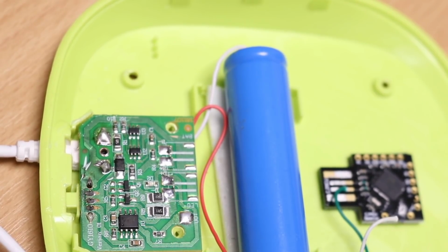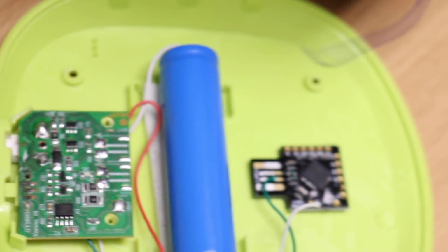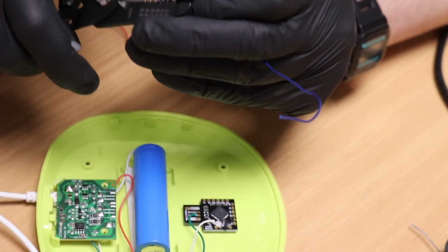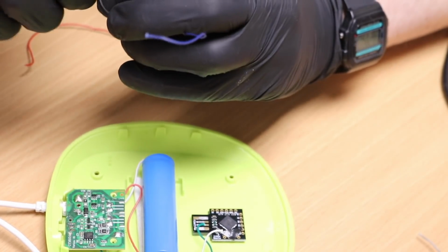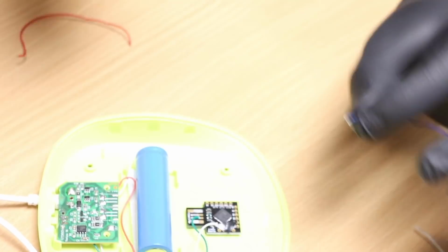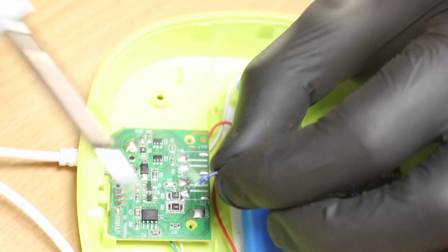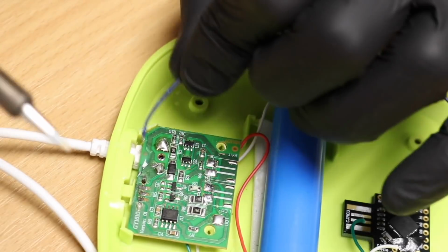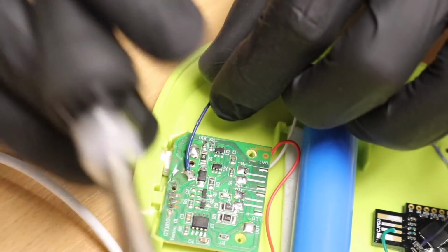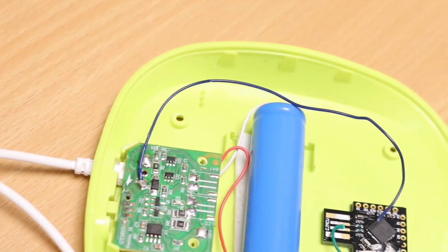Now we need to power our Arduino. So to do this, we're going to take two wires. I'm going to start with the negative wire. I'm going to strip the end of it. Apply a little bit of flux. And solder it. Pre-tin it so that it's easy to attach. Then attach it to the negative point here. So this wire is still not attached to anything on the other side, is it? No, it's not yet attached to the Arduino. Okay. We're just starting by attaching it to the main power source.